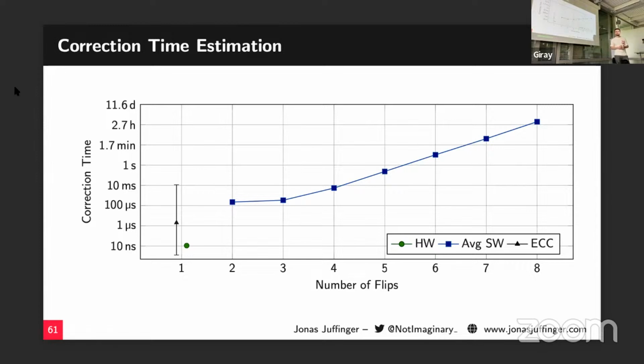But during scrubbing you can also use MAC, right, instead of ECC? Yes, in this case, yes. If you use normal ECC in a state-of-the-art server CPU with ECC, you also have to do memory scrubbing to not have bit flips accumulate.